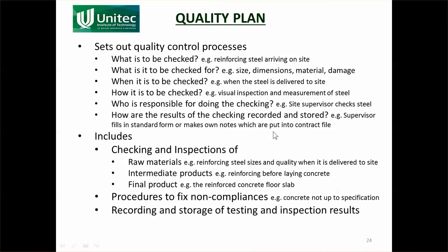Who's responsible for checking? It might be the site foreman, it might be the project manager. How are the results going to be recorded and stored? It's not good enough just to do the checks. You need to record them and store them, because at the end of the project the engineer is going to come along and look at those things and say, have you done all these checks? Can you tell me that this pipe that is now buried was the right type of pipe, was in the right place, it was at the right depth, it had the right bedding, it had the right backfill, all those sort of things there. Now he's not going to be checking all of those. The person on site did, the contractor and the engineer's representative, and they recorded them, documented them, put them in a folder, and that is what the engineer looks at.